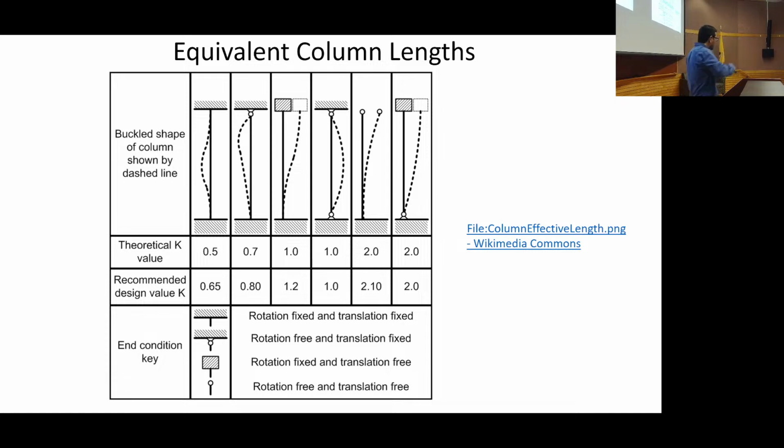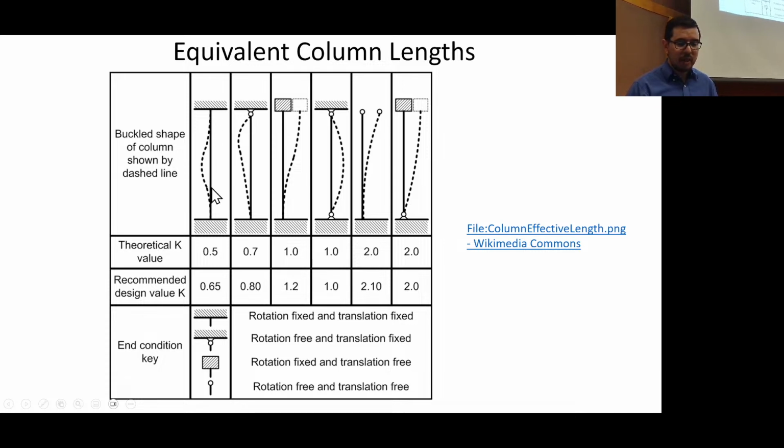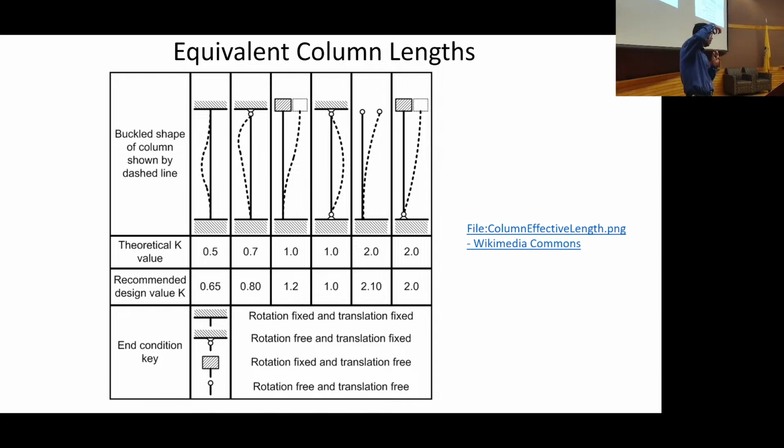So if you have a beam that is fixed at both ends, that means I've got moment constraints at the ends, and also I've got the horizontal constraints, and I'm pushing down. Is that going to be harder or easier to buckle than, say, if I just have a beam that's sticking out and I'm just using my finger on the top? If it's constrained on both ends, it will buckle. And I guess maybe we should go back and just talk about what is buckling.